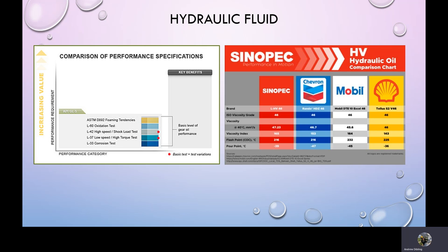There are also other things you want to look at in terms of your hydraulic fluid. Is it hydrophobic? In other words, does it shed water? How is it at conducting heat? Does it foam? And what kind of oxidation does it have? Does it oxidize your components? And remember that it's very critical that your fluid match the seals in your system, and you don't want to substitute hydraulic fluids unless you get permission from the manufacturer of the equipment. You can damage some seals by putting in synthetic fluids if they're designed for mineral oil based. Or if you're using some kind of a glycol-based fluid, you can't substitute mineral oil in that unless it has the same properties, because otherwise you will just damage the equipment. So it's very important that you know what type of fluid you have.